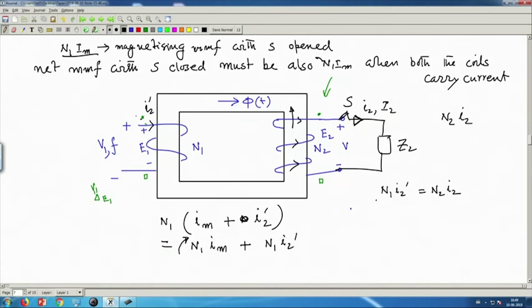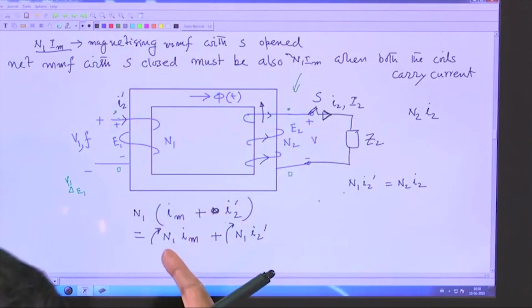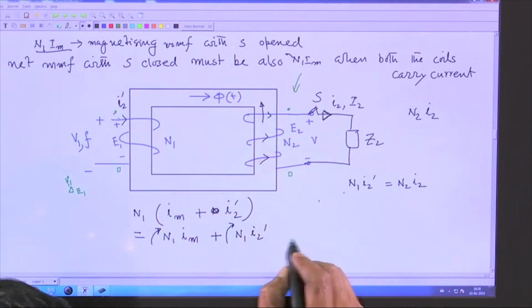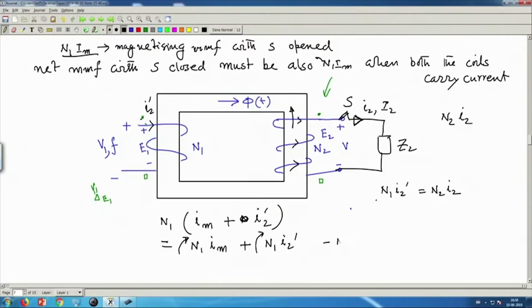From the dot current is coming out, it also creates flux in this direction, clockwise direction flux. And on this magnetic circuit, apart from these two MMFs, a third fellow occurs, which is N2 I2, or I will write plus, create this way.